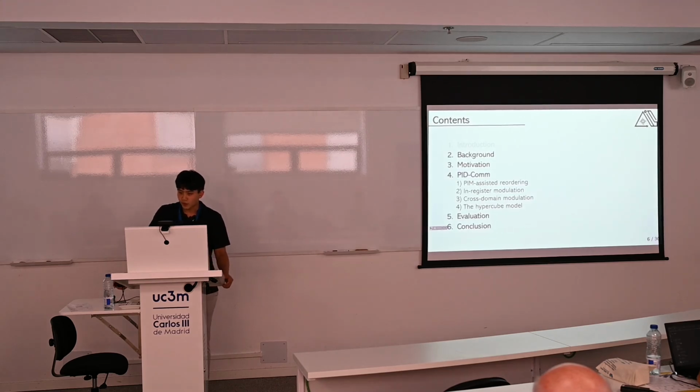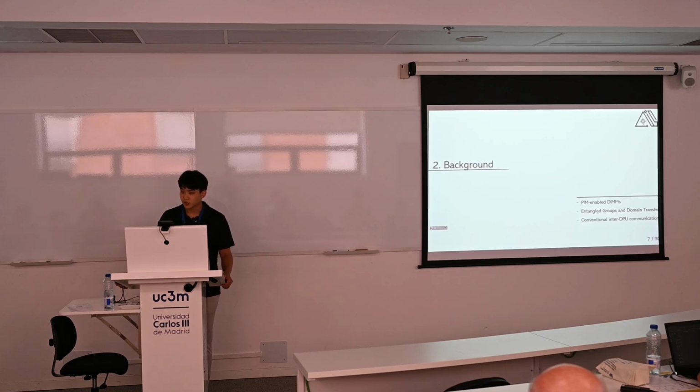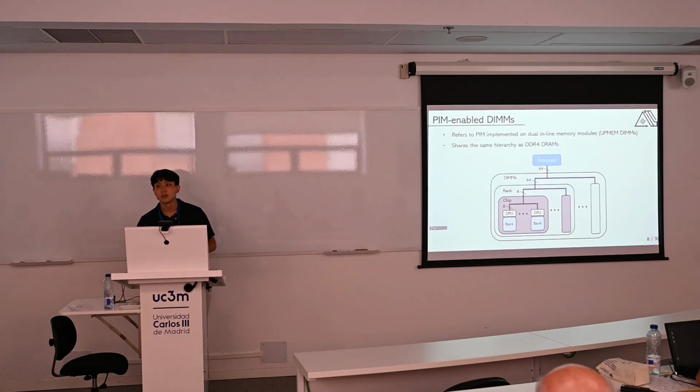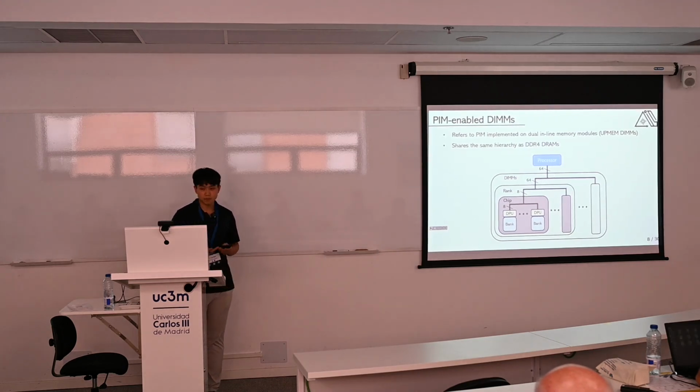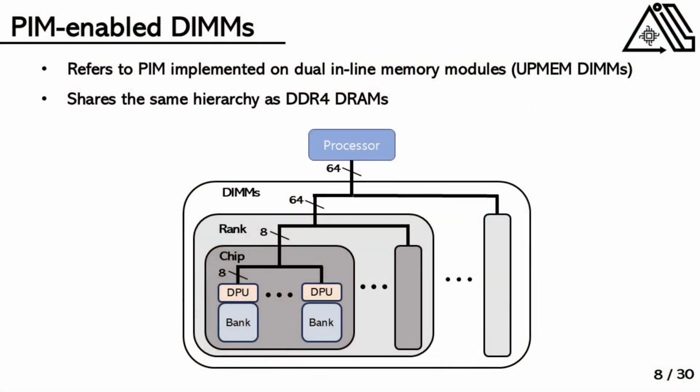Now, just a quick view of the contents, I will cover some of the background of the talk, followed by the motivation of the study. So, PIM-enabled DIMMs, or UPMEM DIMMs, refer to PIM cores implemented on dual inline memory modules. Other than the additional processing units, they share the same hierarchy as DDR4 DRAMs.